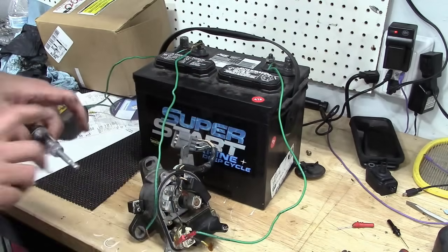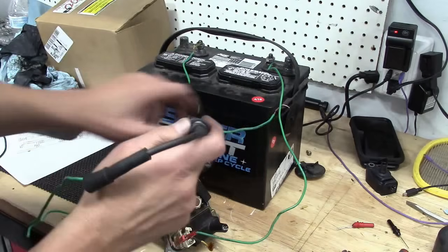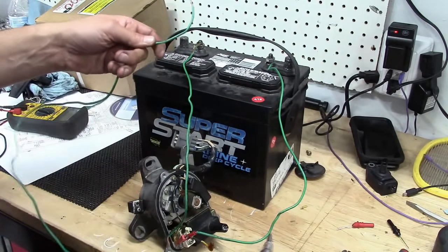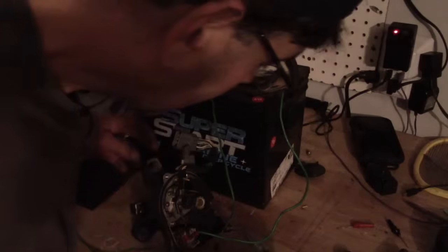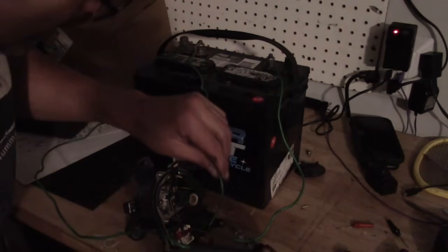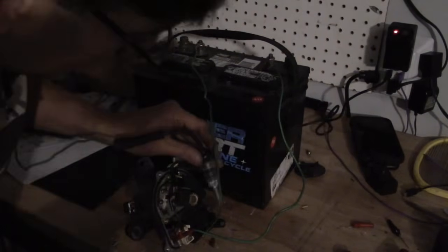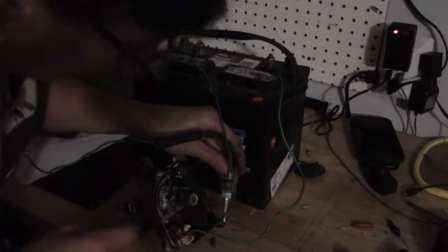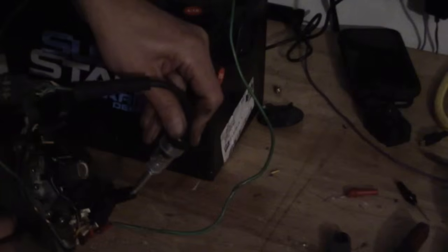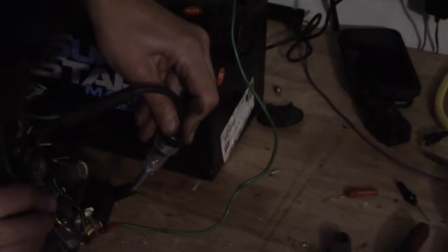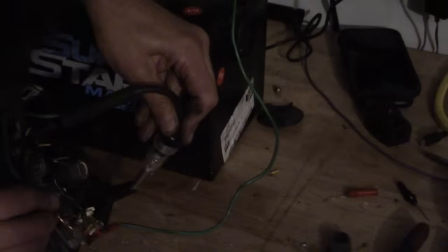So now I just need to get my little test light over here. The test light is to battery negative, obviously grounding. All right, we're going to set my test light into the coil output. Oh, it lights. It actually lights. I don't know if you guys can see that. Let me reconfigure over here. All right, focusing in on the tester right there. And yeah, you can easily see that that's working.